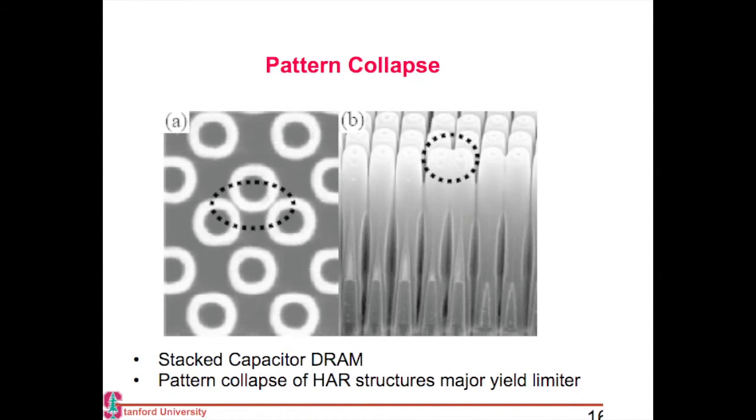So coming back to your question, even though I've etched these structures, how do I maintain their integrity? It's very hard to do. This stacked capacitor over here has an aspect ratio of 67, and inevitably, with any wet processing I do, if I fill it up with a liquid, it will collapse into each other because there will be forces causing bending.